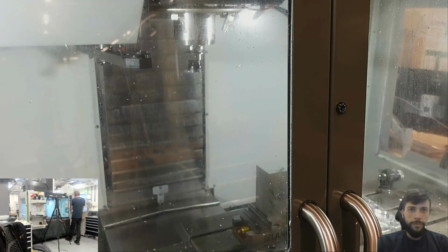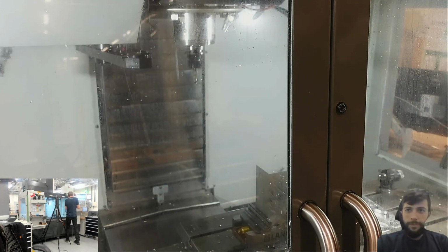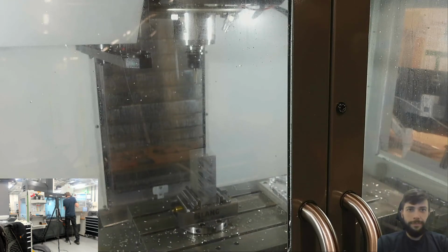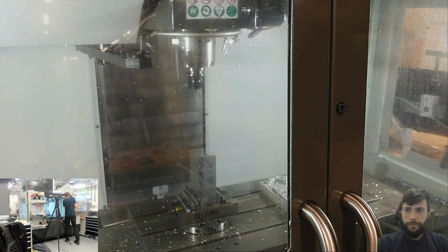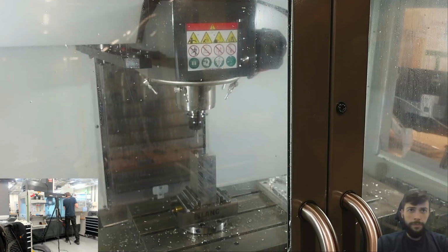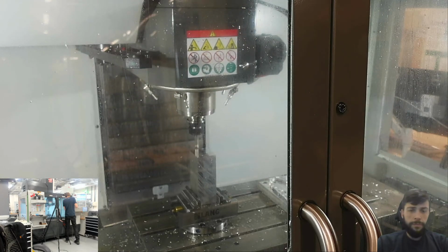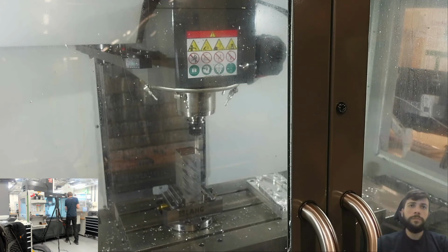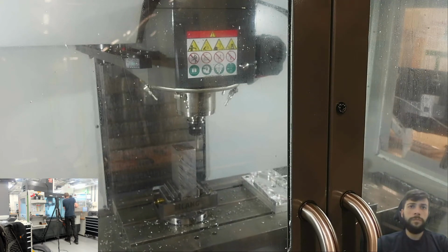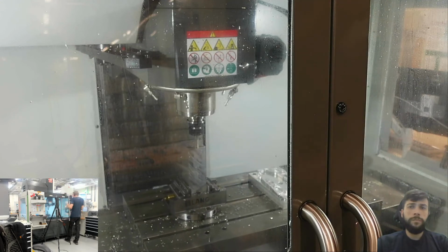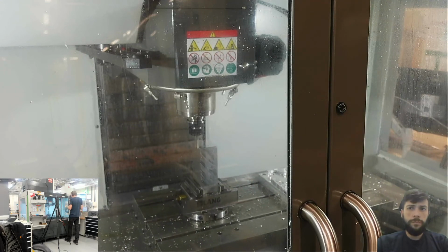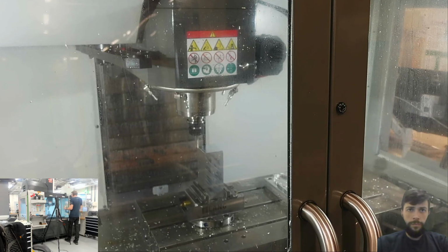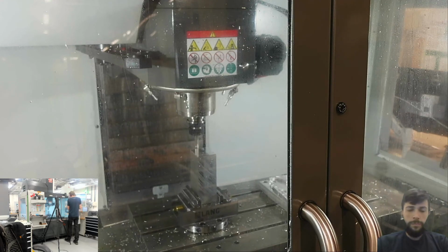So for anyone out there that does anything with probing, this is the basis of everything we do with probing. We're using these macro variables to store the data for where we triggered, and actually then we use that to give us back those inspection results. So it's really powerful, all this NC logic is. We're only touching upon it today, but hopefully we're giving you the building blocks to think about what you can do in your shops, looking at how you can use macro variables and logical programming to actually get a bit more out of the machines rather than just making parts.